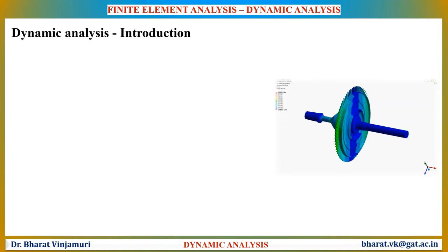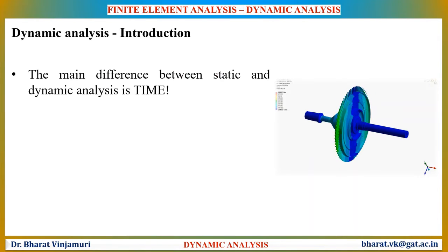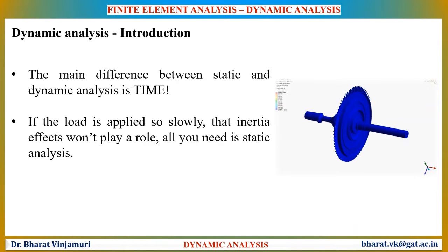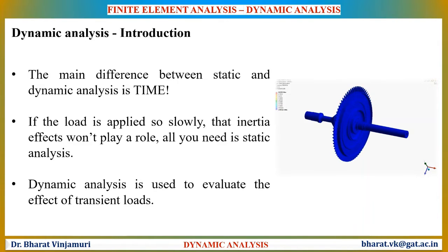The main difference between static and dynamic analysis is time. If the load is applied very slowly, the inertia effects won't play a role. All we need is static analysis. Dynamic analysis is used to evaluate the effect of transient loads, or the loads that change with time. Also, dynamic analysis will involve the analysis of vibrations and their effects.